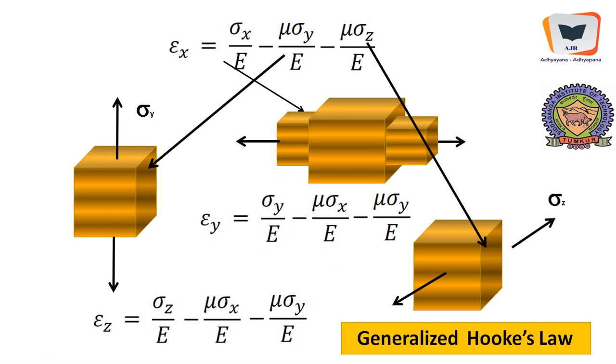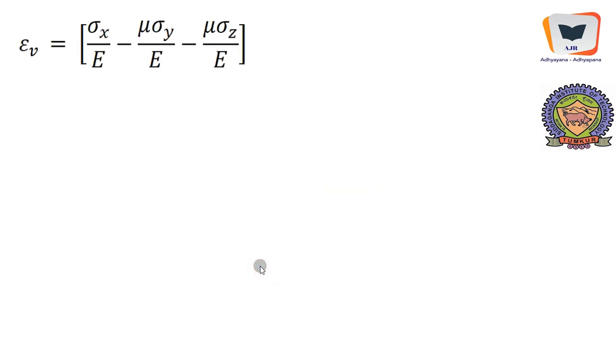That's what we argued. And here, whenever you consider a component which is acted upon by stress in three mutually perpendicular directions, side effect is to be accounted, and the equation is much more than sigma x proportional to epsilon. That is, stress is proportional to strain. Stress is also proportional to the strains that happen due to the stresses acting in some other direction. That is the meaning. That is what we call generalization.